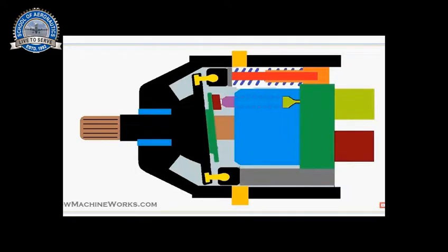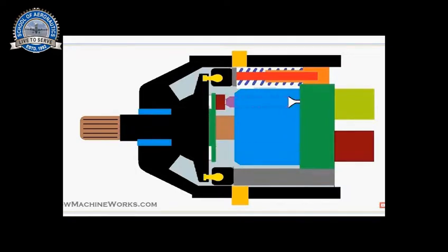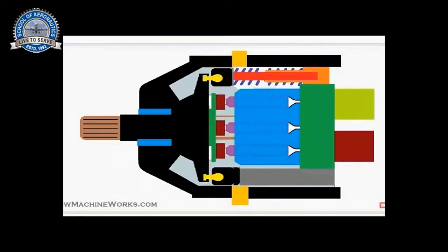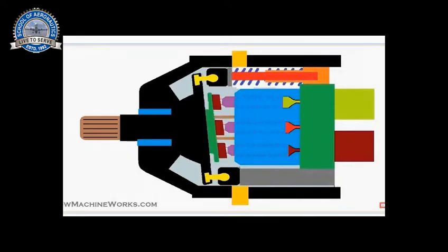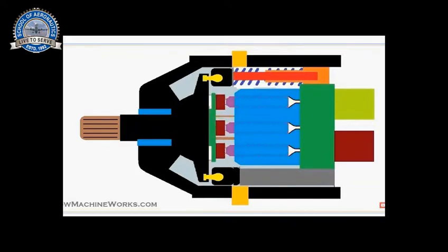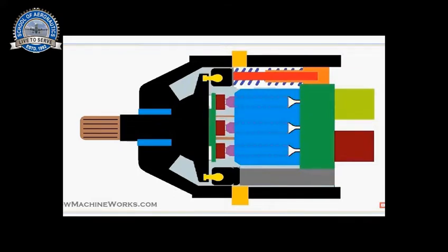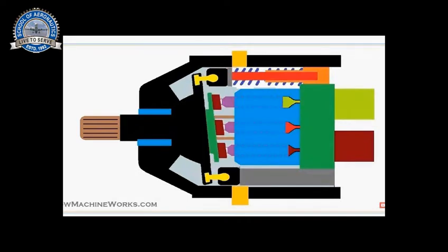So let's say it again. Suction is happening, discharge is happening, suction is happening, discharge is happening at the bottom. So that's it. So we have more number of pistons at the bottom and top. You can see how it exactly works. We have a suction at the top and we have a discharge at the bottom depending on the swash plate angle. So that's how an axial flow variable displacement piston pump exactly works. The variable displacement happens according to the difference in the swash plate angle.